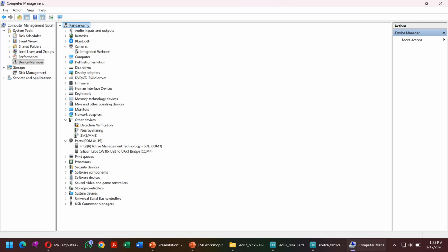Now I will skip the web browsing section for a while. We are going to do the hardware section now. In this hardware section, you connect your ESP8266 through your USB port. After connecting, check in the device manager whether your hardware is connected. Go to the device manager and check that your COM port is connected. As per my requirement, COM4 is selected here. If it is not there, please install a suitable driver and then use it.